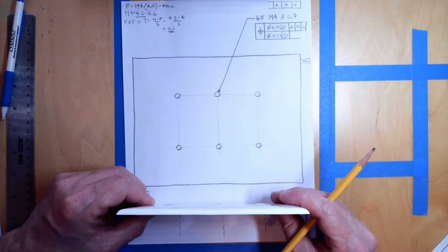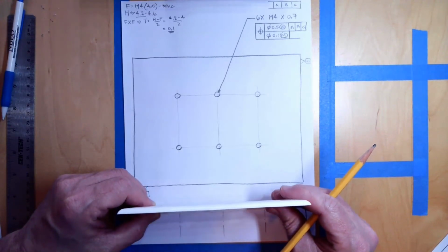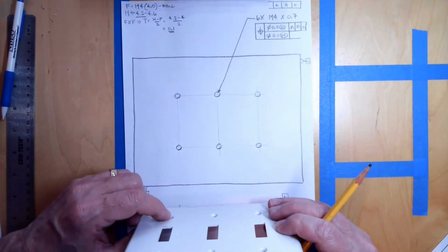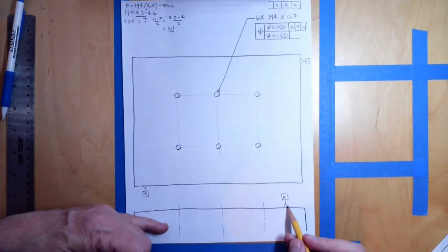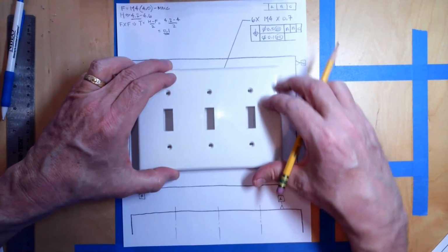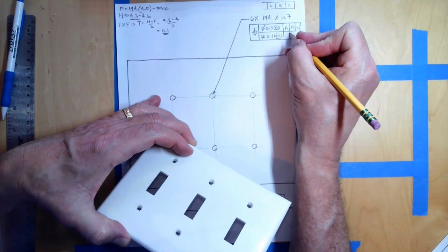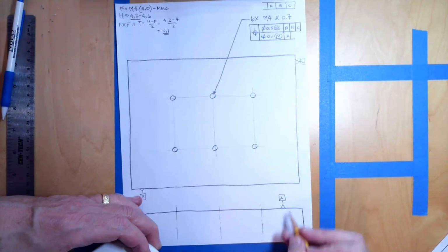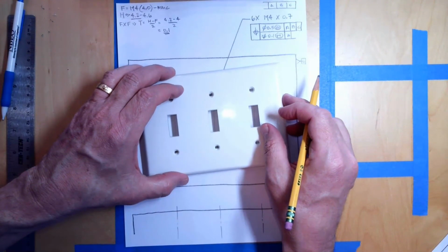If the holes are not perpendicular, then I have problems with the screws going in, right? If the holes are not perpendicular, then maybe I have the cover plate kind of cockeyed. Maybe I can't even get the fastener through there. So I want the holes to be perpendicular to A. Other than that, can I tolerate the cover plate being slightly at an angle? We need A there because we want the fasteners to be perpendicular to A. Can I tolerate the cover plate being at a slight angle?